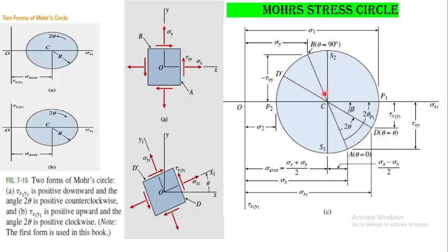You have joined them. Now the other target will be to calculate what will happen if this element is rotated by an angle theta. There are two choices: it can either be rotated anti-clockwise or clockwise. If this element is rotated anti-clockwise, we will move from this origin of ours, from AC, in the anti-clockwise direction. If they say in the question, for example, that this element is rotated 20 degrees, then we will move from this point, from the origin. These values, the first origin, is very important.